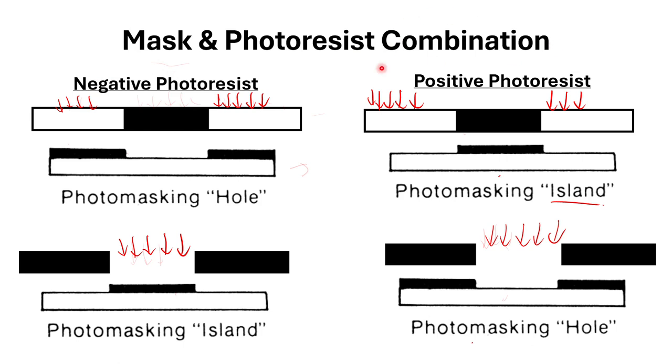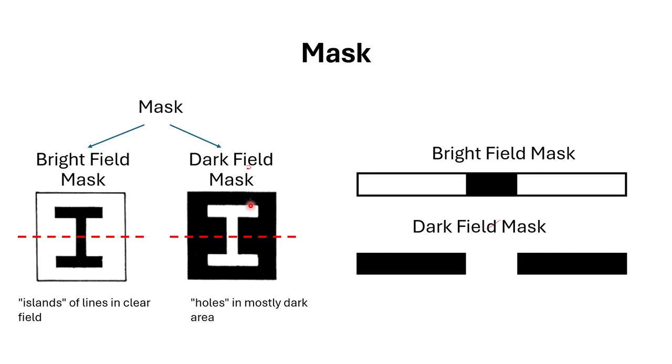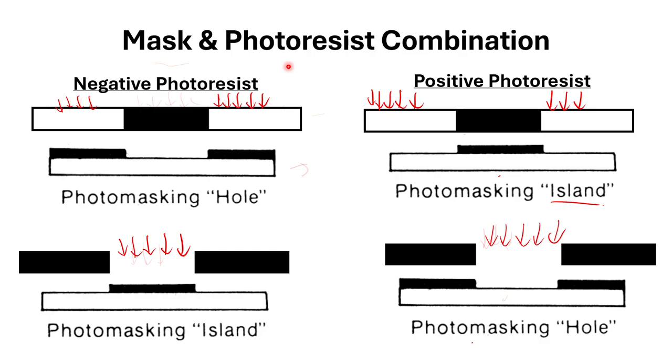A mask is kind of permanent. Let's say we want to do a patterning where we have drawn a mask like this, but we want to expose the region that is eye shaped. We want to create a pattern where this eye shaped region is getting exposed. Then we can use a different combination of photoresist so that we'll get the desired pattern. That is what I wanted to convey about this mask and photoresist combination.